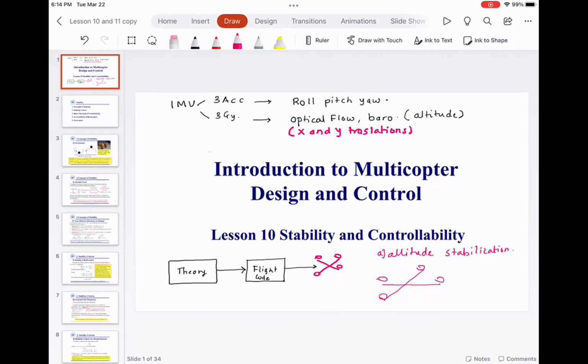How would we do the barometer loop? If you want to maintain the height with the barometer, all these props, if the height is low, should speed up. If the height is high, then speed down. Are you with me? So we would actually write those loops inside MATLAB, put them in the motor mixing algorithm, and then flash it onto the Mambo, and we'll see if you are able to achieve the stable hover. That is always the first step, stable hover.